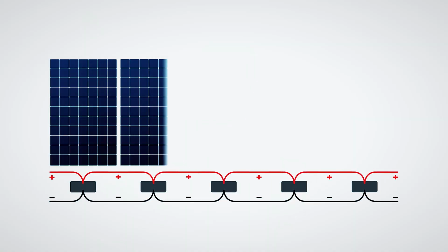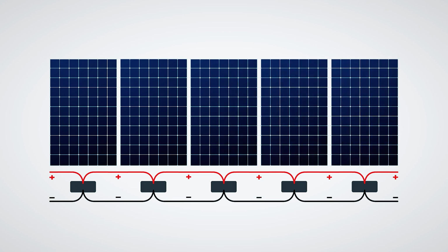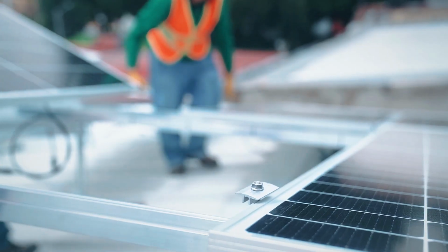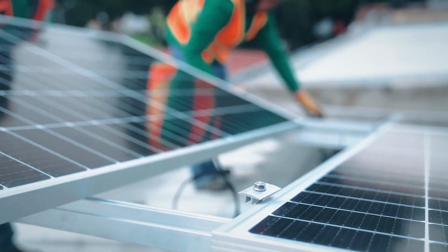What are parallel solar panels and how do they work? In a parallel configuration, solar panels are connected side by side with positive poles connected to each other and negative poles connected to each other. This setup allows the voltage to be the same as that of the individual panels while increasing the total current. A parallel connection will allow your solar panels to produce energy without exceeding the operating voltage limits of the generator or inverter. Parallel connections are useful when the goal is higher system current.